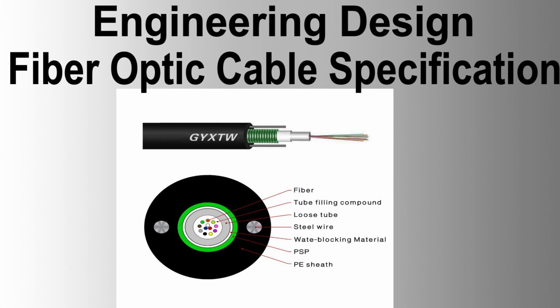Impact resistance. The test shall be performed per IEC 60794-1-E4 according to the impact load requirements shown above. After impact, a permanent or temporary average increase in optical attenuation value greater than 0.1 dB at 1550 nanometers shall constitute a failure for FOC installed in HDPE conduit. The cable jacket and armor shall not exhibit evidence of cracking or splitting.